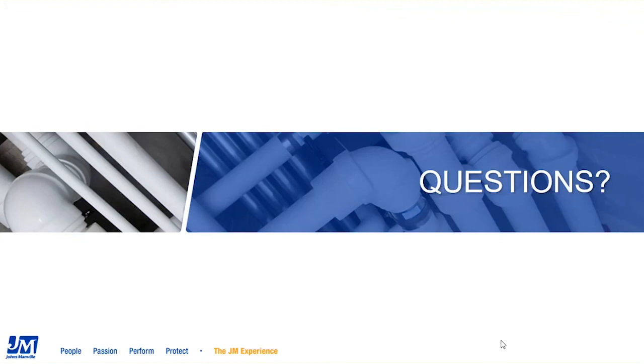When possible, it would be with the full thickness. For that particular slide, we were showing how it would be filleted, and that might be where you would install the pipe insulation at a support. In order to prevent the pipe insulation from being crushed, we would insert a different type of material with higher compressive resistance, like foam glass or something like calcium silicate, or even a polymer foam material. Excellent, thank you.